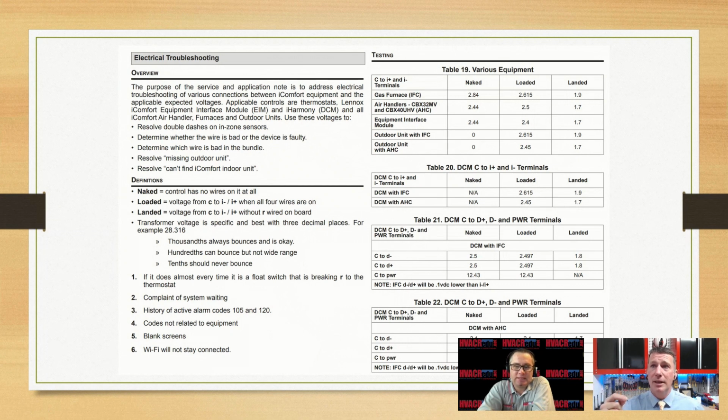Check my voltages. And if my voltage for my indoor unit is good, I open the closest window, I go grab some fresh conductor, and I throw the old one out the window. That's exactly what I do. And so I run a fresh conductor and then retry it, because you will have nuisance issues with communicating wires on existing thermostat wires that didn't have any problems when you're running a contactor. When I had a contactor, my current was going through the conductor, right? I was utilizing the entire circumference of my conductor to get my current through to create a load on my contactor. With communication, a lot of times I'm running around the surface of it.